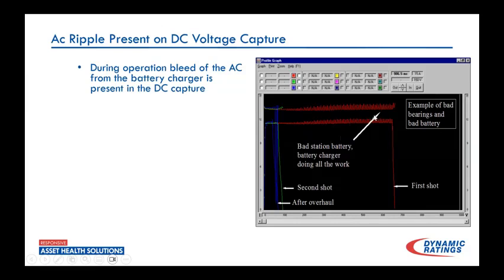And again, without this capture, it's hard to see with just regular monitoring of your battery system, because it does happen so quickly most of the time that without this type of capture, you're just not going to make the association. So this is another useful point of these first trip type testing, and another thing we can collect from this waveform data.